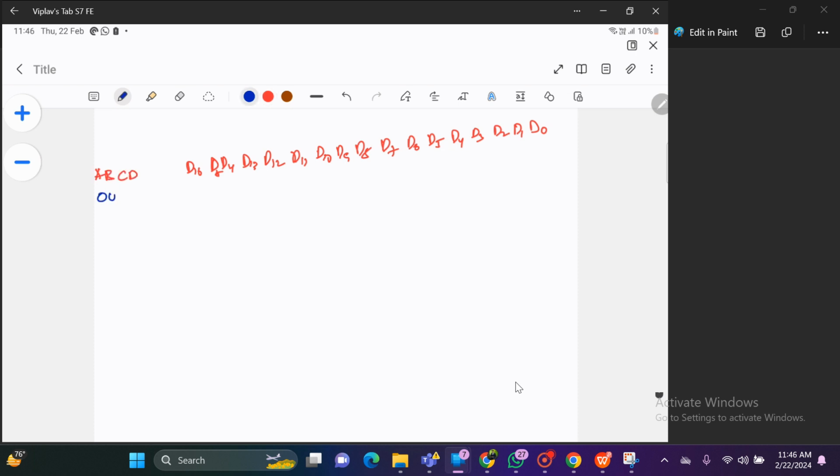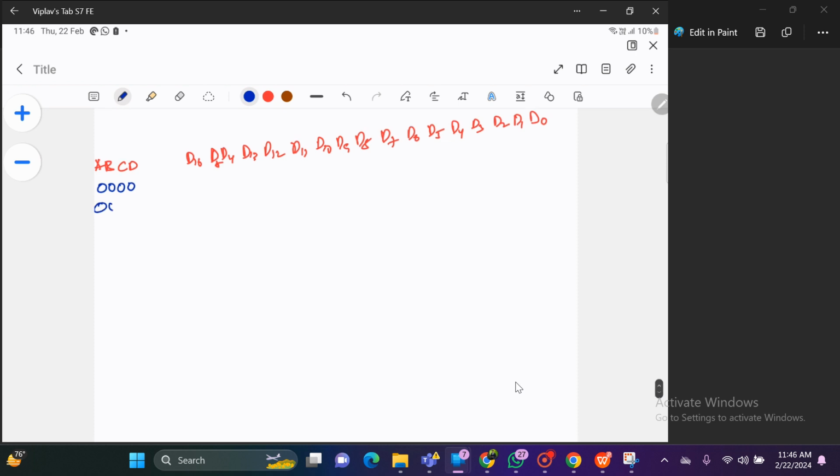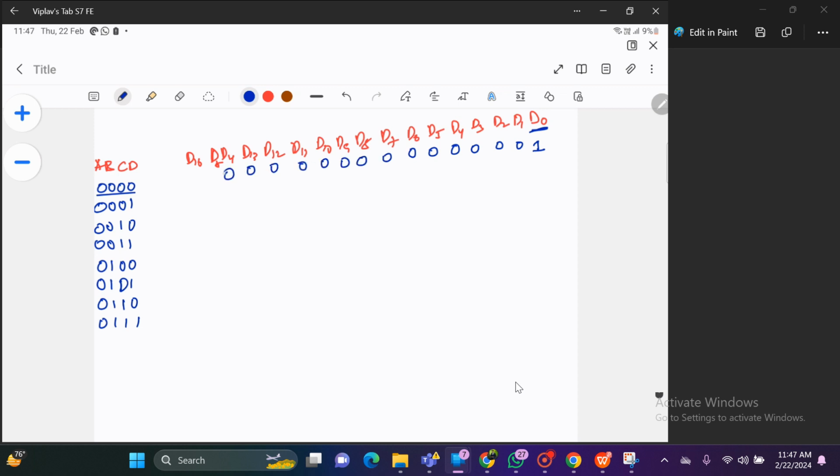So starting from 0, 0, 0, 0, then 0, 0, 0, 1, then 0, 0, 1, 0, 0, 0, 1, 1, 0, 1, 0, 0, 0, 1, 1, 1, 1, 0, 1, 0, 1, 1, 0, 0, 1, 1, 1. So like that combinations. Now in this output, how it will be? So 0, 0, 0, 0 in the sense the 0th pin is enabled, d0 will enable, remaining all 15 will be 0. Then 0, 0, 0, 1.